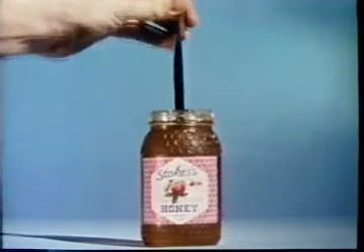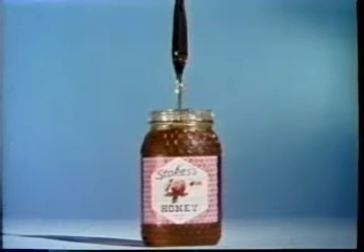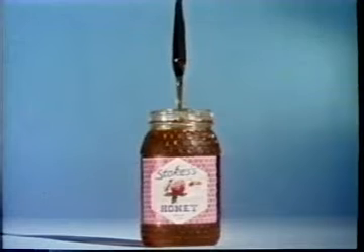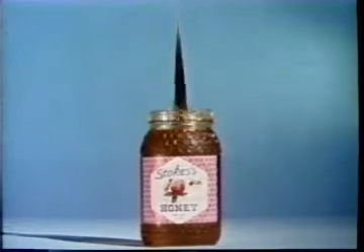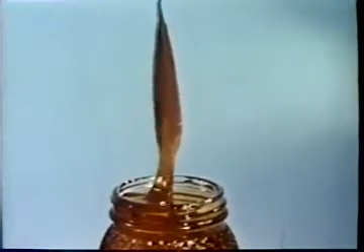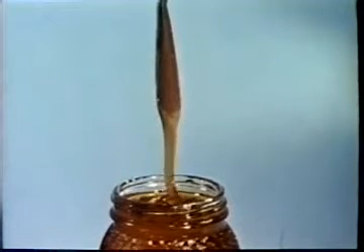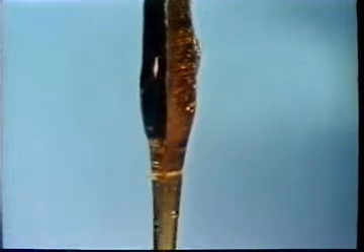Pulling a knife from a pot of honey, for which mu is very large, demonstrates two properties of a viscous fluid. It can resist both tangential and tensile stresses. The honey can only be lifted by a tangential force exerted by the knife's surface, which must be transmitted through adjacent layers of the honey. The stretching of the stream as it leaves the knife gives rise to tensile stresses across horizontal sections. These make the speed of falling much less than if the honey had been falling freely.